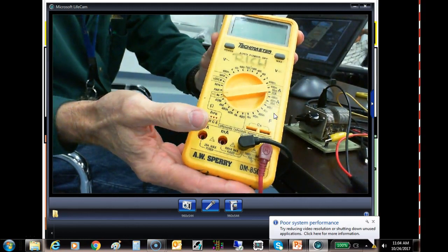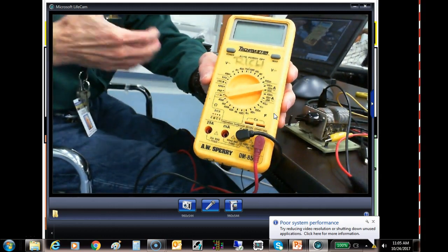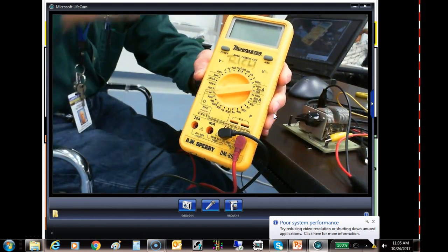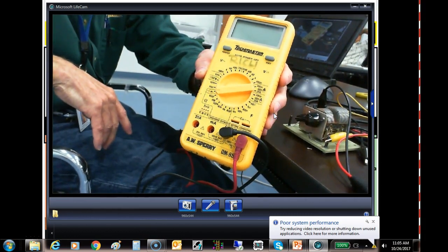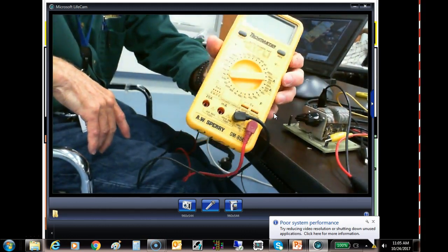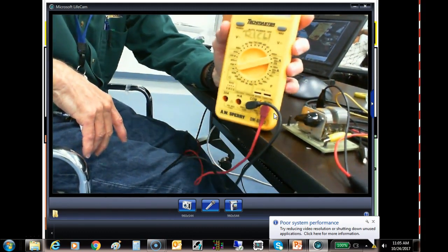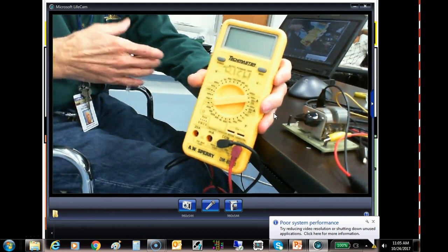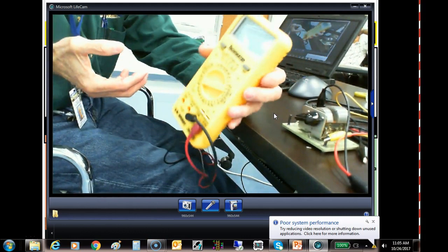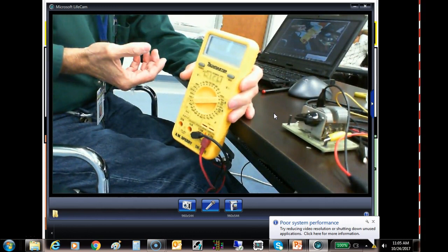But a lot of these meters, people have problems with them where they'll get into a circuit and then a big energy pulse will come in and the meter just disintegrates and blows up. So they came out with different categories for where these meters should be used. Basically it protects you against, if you get a meter that's got a 2,000 volt AC scale on it and you put it in 50,000 volts, and it's because of stupidity.